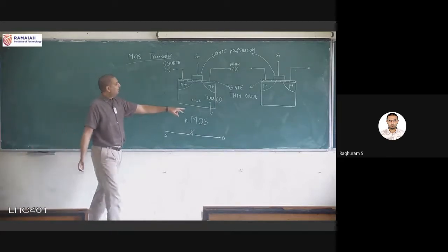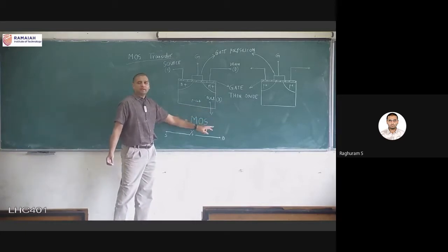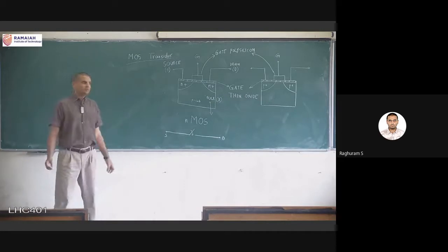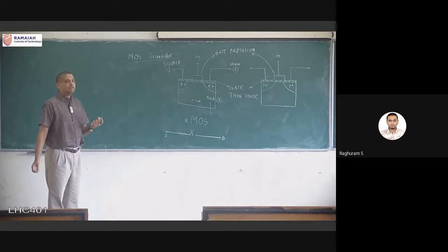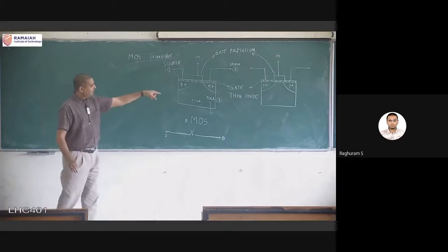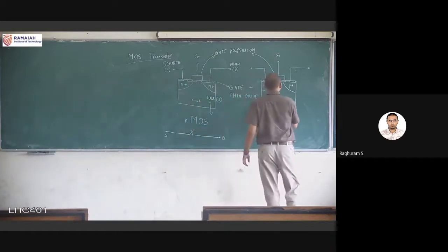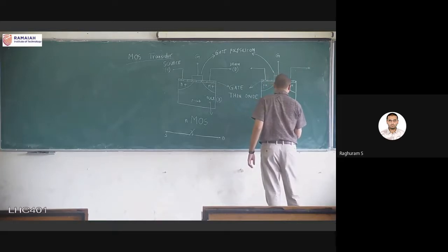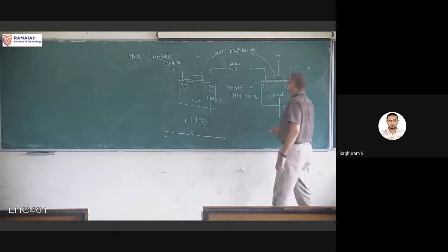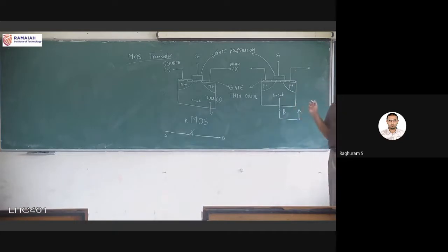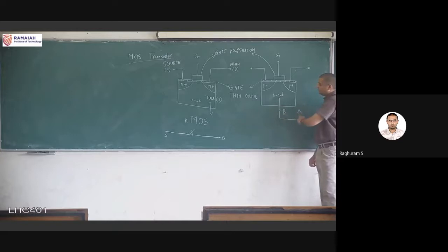The fourth terminal, in this I have shown it is connected to ground, and you can try to remember, we have discussed this before, why it is connected to ground. But it should be connected to ground, otherwise it will not work at all. Okay, similarly on that side, the bulk terminal, since it is a PMOS transistor, has to have an N-type substrate or an N-well, doesn't matter. But that N-well or N-type substrate should necessarily be connected to power supply or VDD.